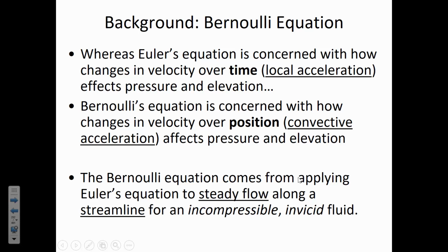Yeah. So using Bernoulli's equation, we can make the assumption that the acceleration of the fluid is constant. Is that a safe assumption or not? Because as I understand, there's a steady flow, so the velocity must be... Remember, there's 2 kinds of acceleration. Right. Local. We assume that the local acceleration is 0, but there's a convective acceleration that's not constant, because if we have a nozzle, the convective acceleration will be different in different locations. Okay.